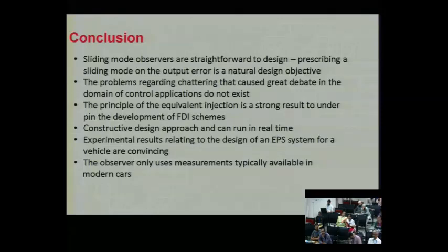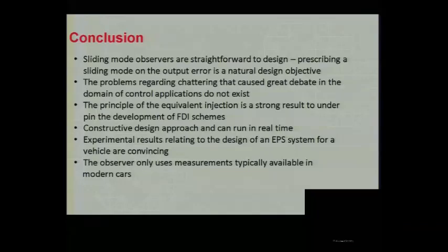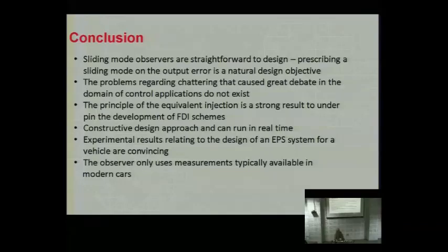So I wasn't using a classical one, largely because I often don't use higher order sliding modes myself. I think with most things you can do it with a conventional first order sliding mode. But my collaborator uses a lot of higher order sliding modes. So for that one, we were using the super twisting algorithm, which is a second order sliding mode controller, or a second order sliding mode injection, because we're using it as an observer. We will see about that tomorrow.